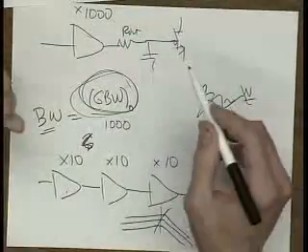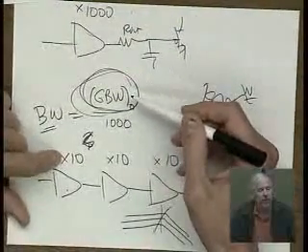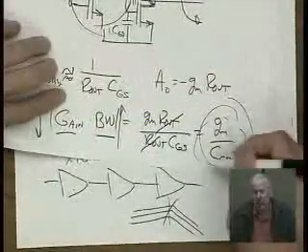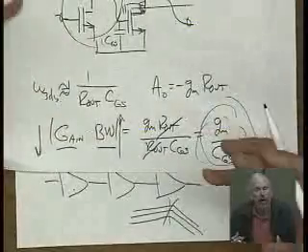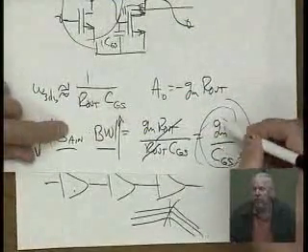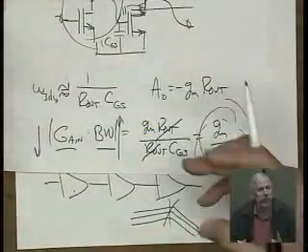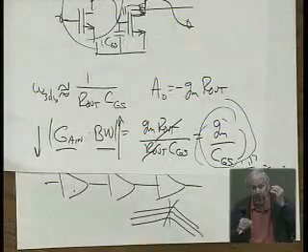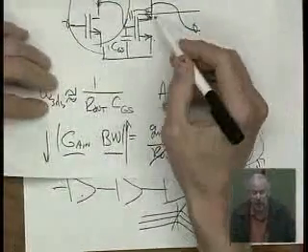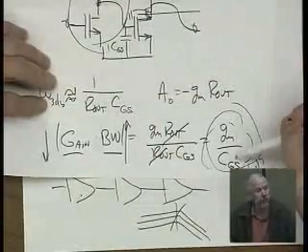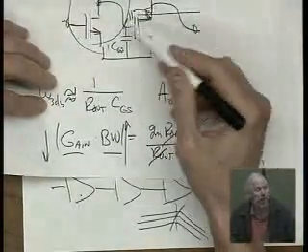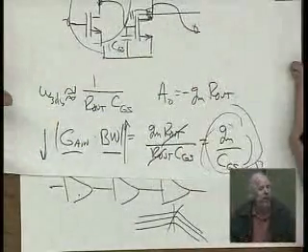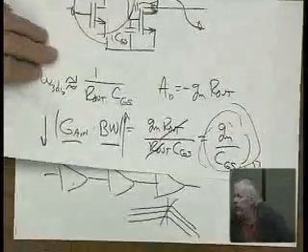Different topologies will have different gain bandwidth products, okay? But it's really hard to beat this number right here. And so if you want to get an estimate of what's good or bad for your circuit, calculate gm over Cgs of one of your transistors, figure out what gains you're asking for, and you can see if you're getting a reasonable bandwidth, right? You can see if you didn't cascode this, you get well below this number, because the Miller capacitance would come in. And you would see you're well below what you could do if you fix the circuit up a little bit by cascoding it. Then the other good idea we had in office hours.